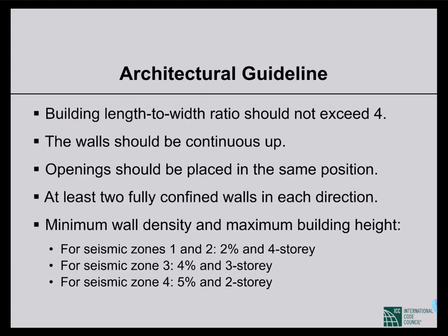The walls should be on top of each other like load-bearing walls. So we cannot have walls in any place on the slab like we do for RC frame structures, where we can place walls in between any place on the slab. We cannot do that in this type of construction. The walls have to be on top of each other. It should be continuously up.